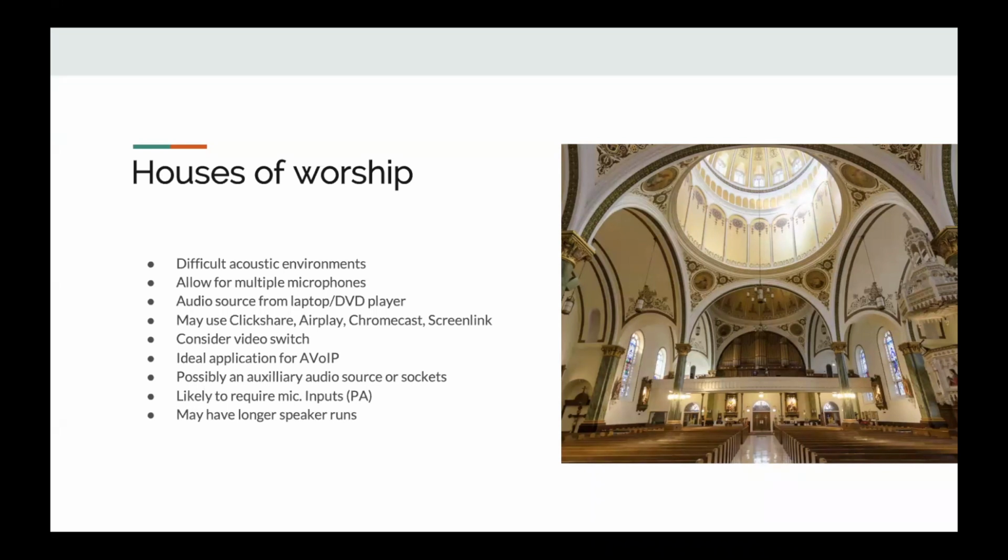Also, you'll find that cable runs aren't very easy, where normally you might hide cables under floorboards through joists, etc. in a residential installation. Most houses of worship are beautifully decorated and designed, and they don't want Cat5 nailed up the walls or sticky conduit. So quite often you have to take elaborate cable routes to get from one point to another.